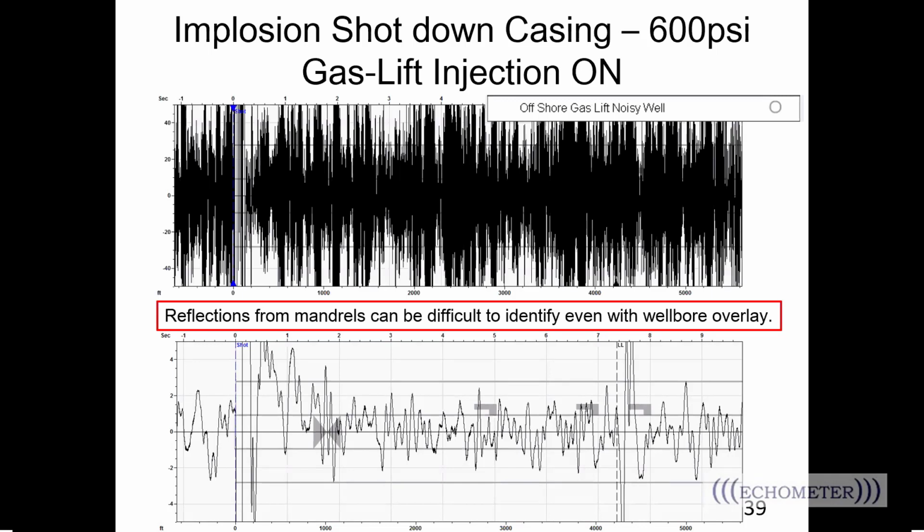So you can see for 15 minutes the pressure measurement at a 5-second interval from the fluid level shot. So on TAM, shooting a fluid level, you'll see the liquid level or you'll see the operating valve. But if you keep on measuring the pressure, you can see that the pressure is leaking off. So just look at the casing pressure buildup curve.